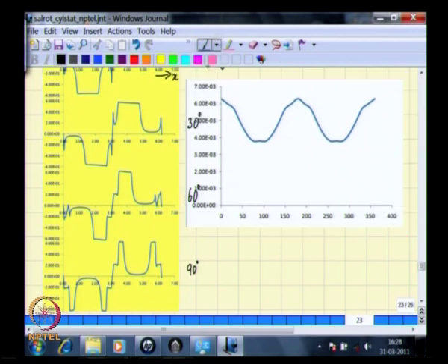Now the x axis gives the rotor angle and the y axis describes the inductance. Now you see that the inductance waveform is not all that distorted. Even though the flux density wave shapes are going to change as the rotor rotates, the inductance wave shape appears like a rather smooth curve, and in fact it may be feasible to approximate this by a sinusoidal